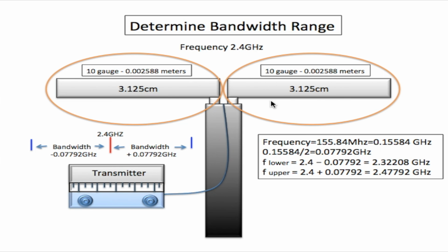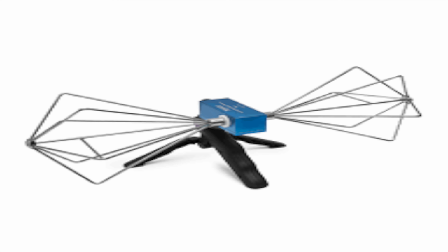The dipole is a well-designed antenna. However, increasing bandwidth with thicker wire beyond 10 gauge is limited, and the thicker wire is also harder to work with. I'll be talking about how to achieve higher bandwidth in upcoming videos with antennas like the bow tie, biconical, and spiral.